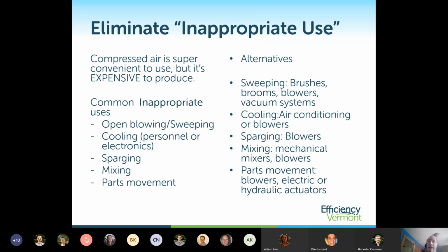But you have 100 psi of air doing the sparging. And every psi is equivalent to a little over 2 feet of water. So with 100 psi, you could sparge a 50-foot bath, versus a bath that's usually only 2 or 3 feet deep. A blower can do 2 or 3 feet of sparging a lot more cost effectively than a full compressed air system that, remember, you've also dried, and then you're putting that air into a wet bath.